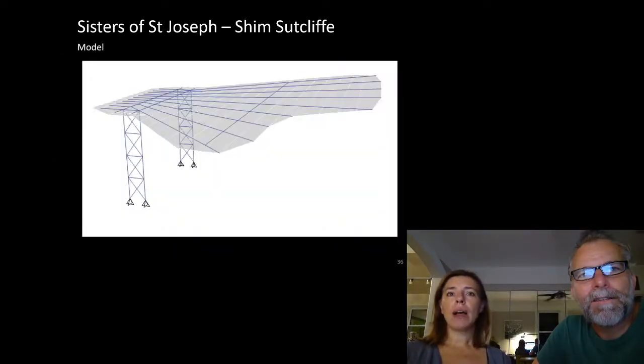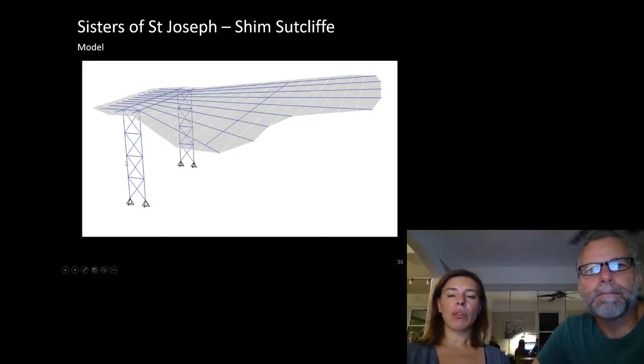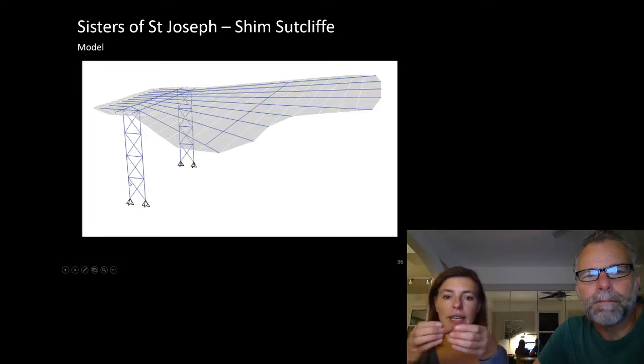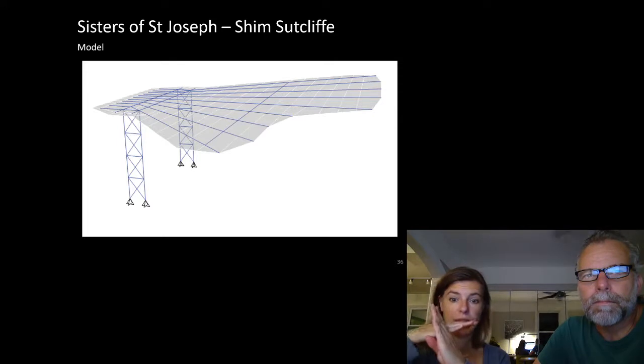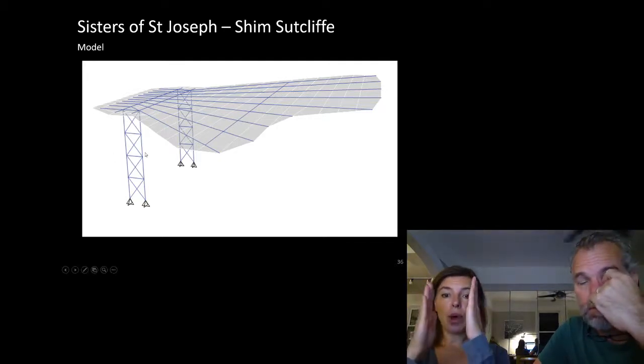So here was my structural model. These modeling softwares often model things as one element. I needed to model the stiffness of that concrete column, but normally it would be just a line, and I also needed it to be my couple. So what I did was, acknowledging that concrete is this overall shape with steel in it, with ties that are dealing with shear, which we often can represent as diagonal members, as you guys remember in our trusses. That's the equivalent of our shear in an element, and top and bottom chords.